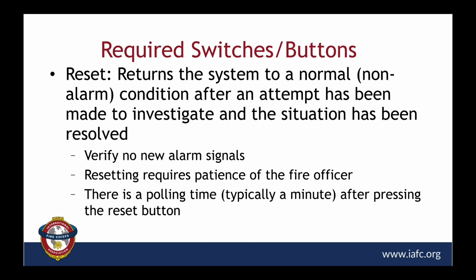But on the more complex addressable analog systems where they're networked, et cetera, the code allows up to X number of seconds, I think it's about 200 seconds, for these panels to go through an alarm restalling, reinitializing process. So that could be a minute or two. So when you go through the reset process, don't be alarmed if you suddenly see the machine taking over and going through a matter of verifying all the devices and doing its thing. It's doing what it's supposed to do.